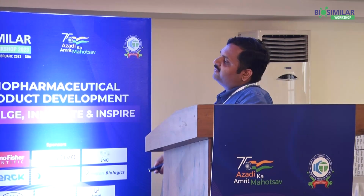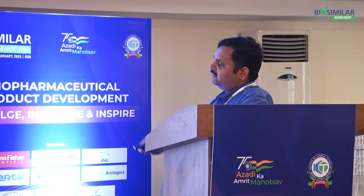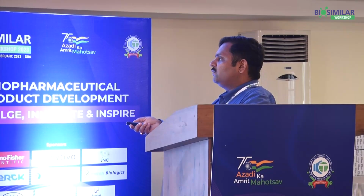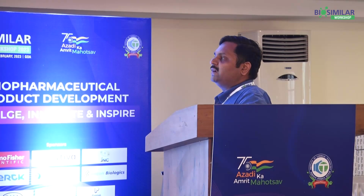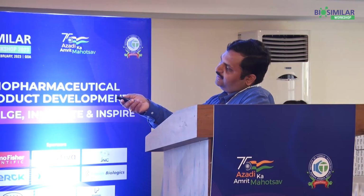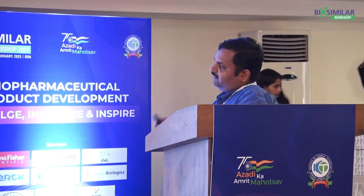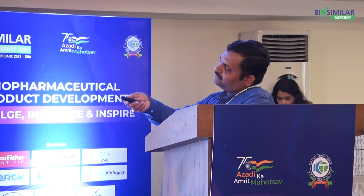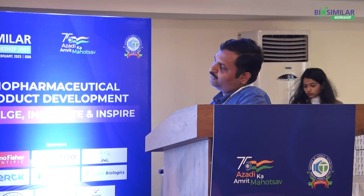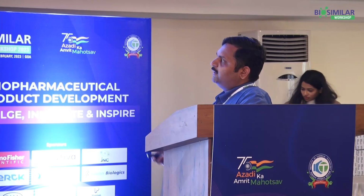So now the parameters derived from these predictions, as well as the mass transport parameters, were used further to predict the breakthrough curve at 15 mg per ml. And you can see, at a 2-minute residence time, the same was validated with the actual experimental data. The curve was fitting well, and you can say with 5% error, we were predicting really well with 15 mg per ml.